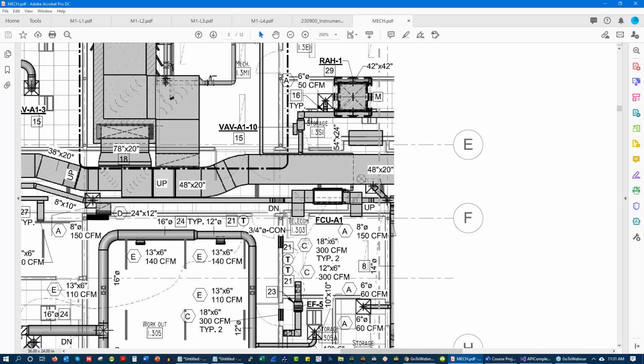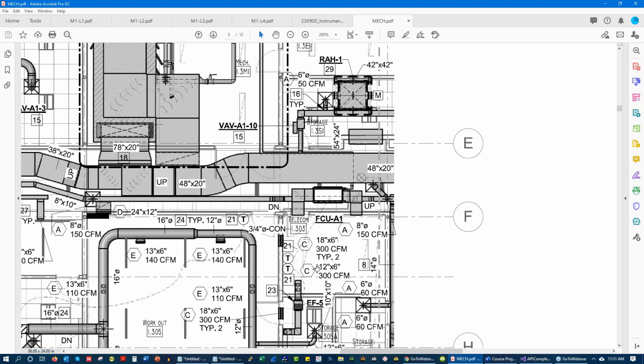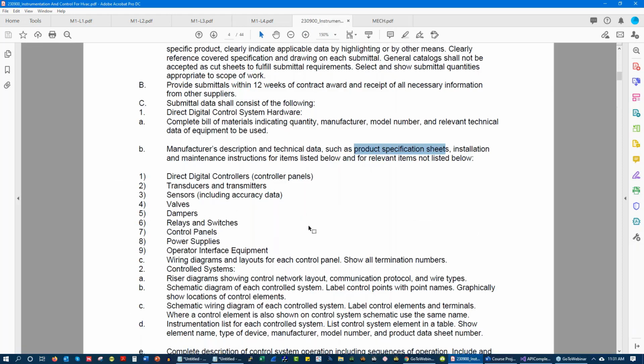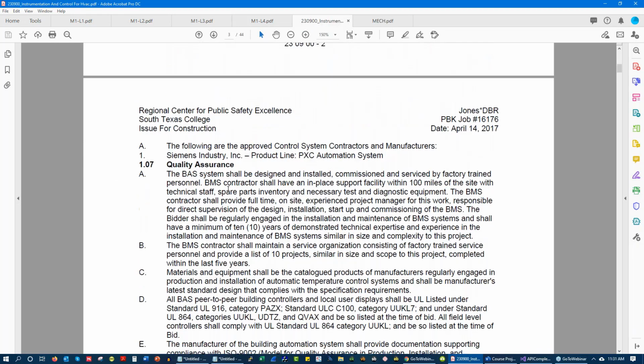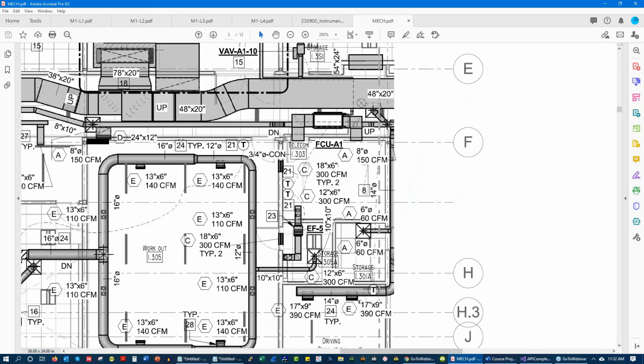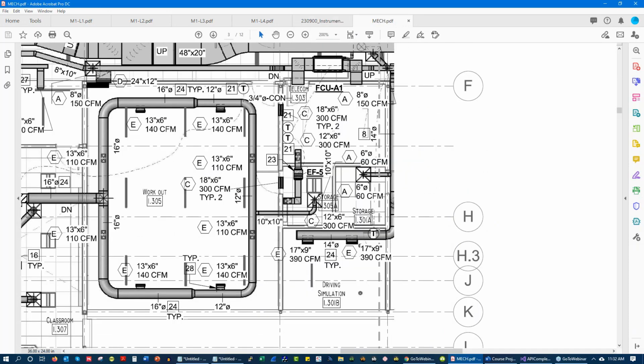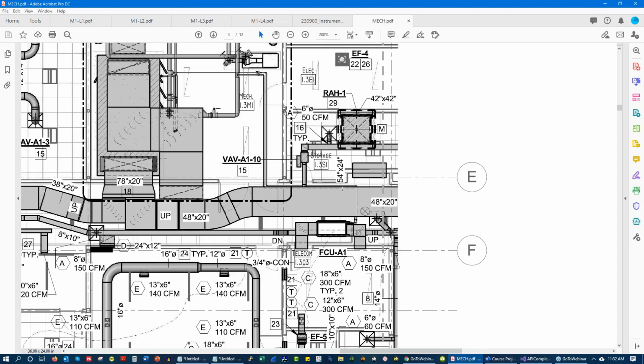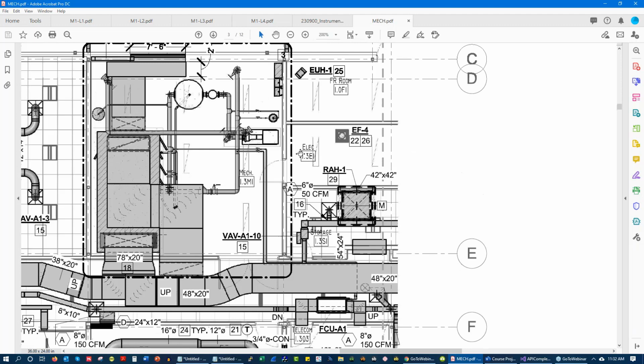And so what happens is you have your supervisory device, and then you figure out, okay, this is BACnet MSTP, which we know from our spec, right? We would read our products and figure out what we're using as far as control line. And then we would just go and run our comm trunk. We would sit there with our electrician for about 30 minutes to an hour, or a couple hours depending on the size of the job. And we'd say, oh, we're going to have a controller here. And then it's going to go from here to here. And then we just bounce along.